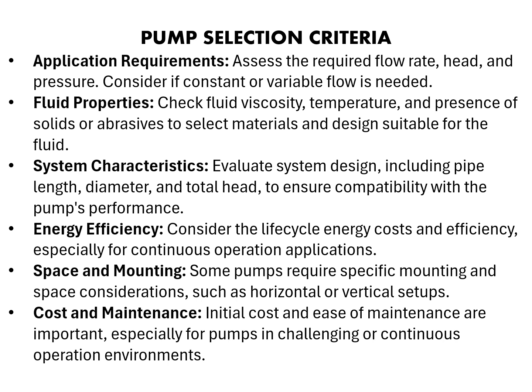Then system characteristics, that is, the length and diameter of the pipes and everything in the mechanical system. Then energy efficiency, which plays a role depending on where we use it. Space and mounting: how much space is available to place the pump. And cost and maintenance, which should not be high. These are some of the pump selection criteria we have gone through.